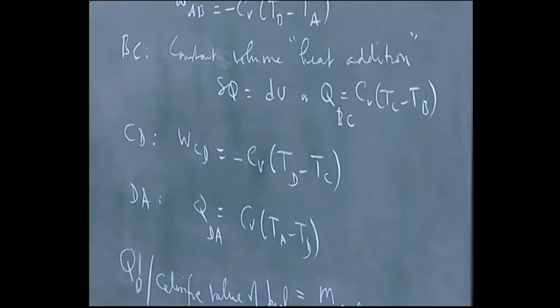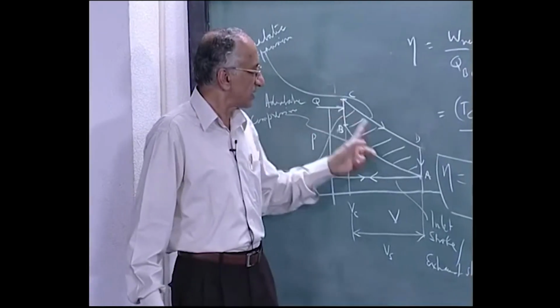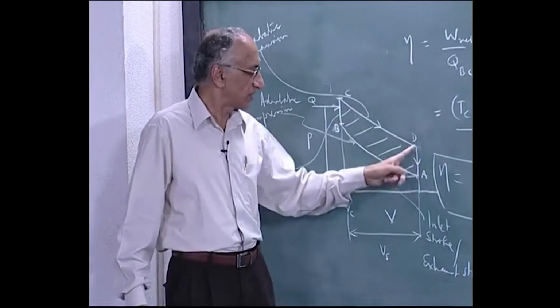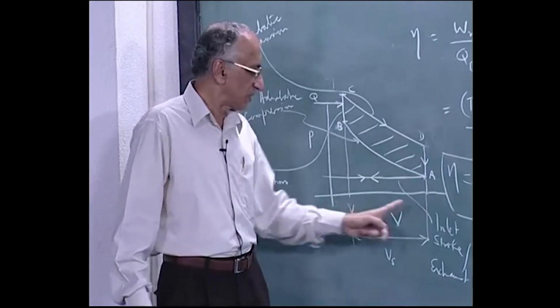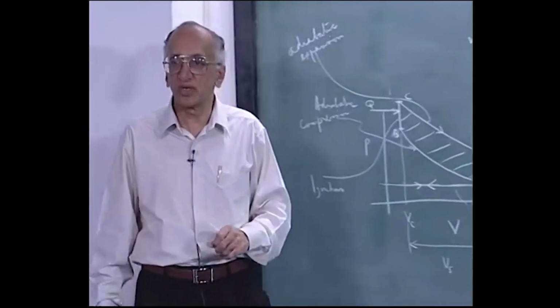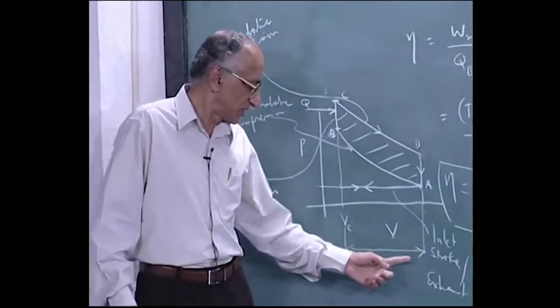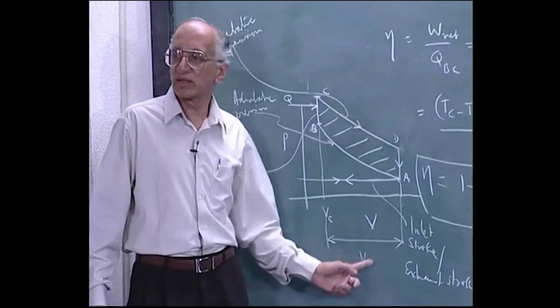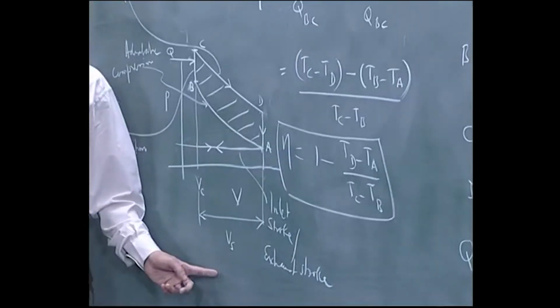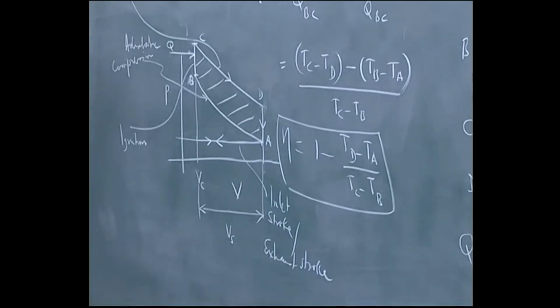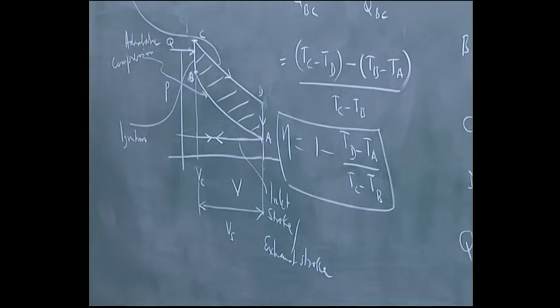So I can calculate that temperature. So I can calculate these conditions and then these conditions again, this is an adiabatic expansion. Once I know these two I can calculate here, because everywhere the volume is fixed, it is fixed by the geometry of the system. So when they say 1.3 liter engine, they usually mean this is 1.3 liters Vs. So if you have a BMW 5 series, 530, then 3.0 liters, 3 liter engine, it's supposed to be a very big engine.